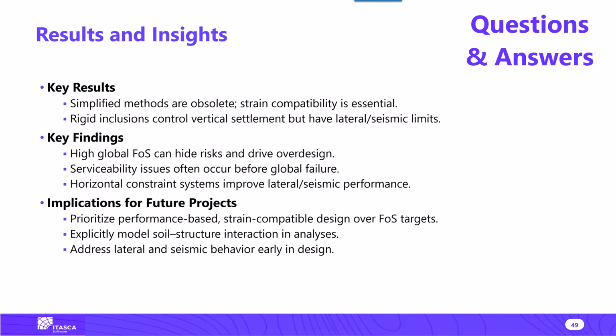Great. Just a follow-up question to that: how were the properties for the different structural elements determined? Well, you need to know the material. If it's concrete, you need to know the UCS. From the UCS, a 28-day standard, you have an idea of the FCK, and from the FCK, you can calibrate the constitutive relationship for the 1D element.